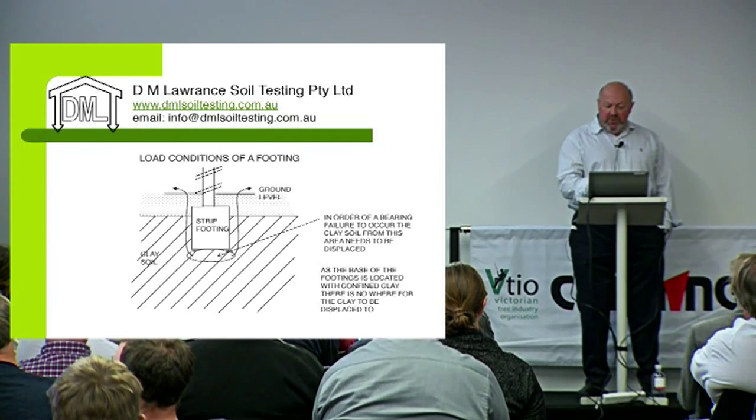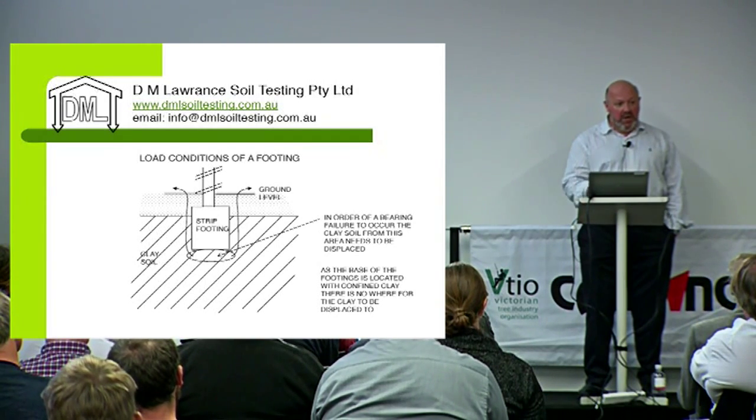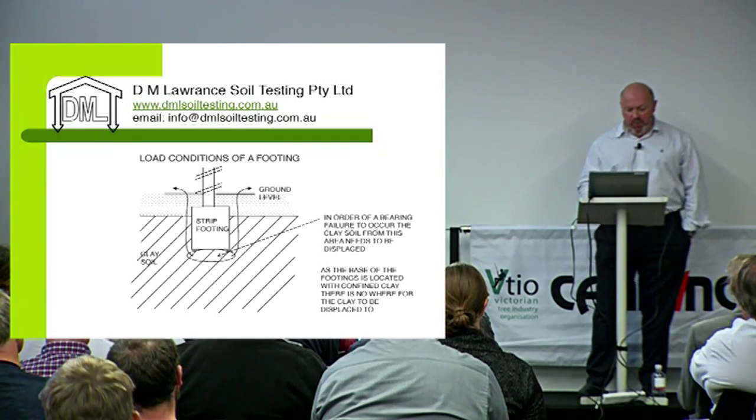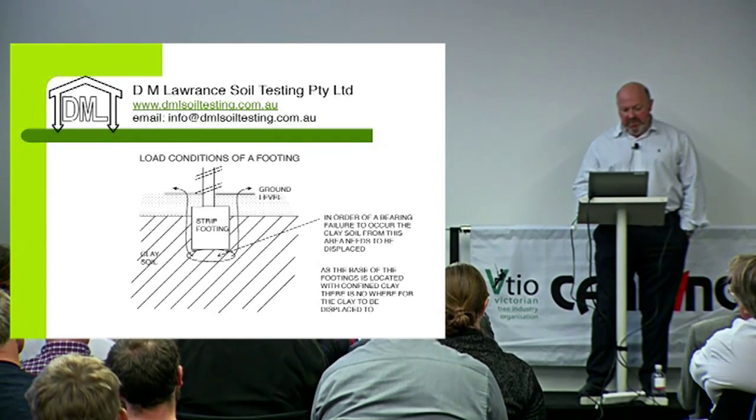The only issue where this does happen is where someone comes along and does an excavation of a basement or a trench right next door to the footing and creates a void into which the clay could move. That's an issue. But when you've got a fully confined clay, bearing capacity does not occur.